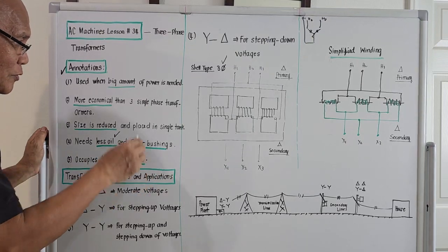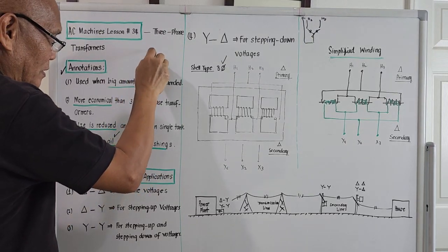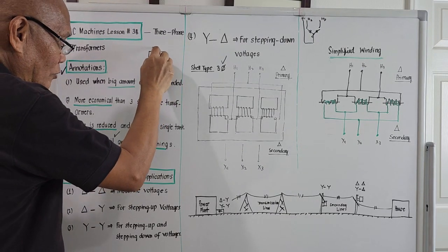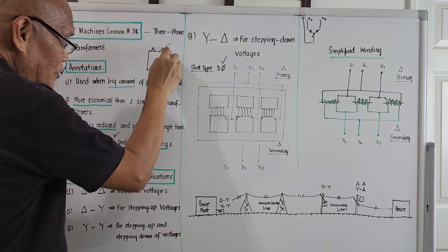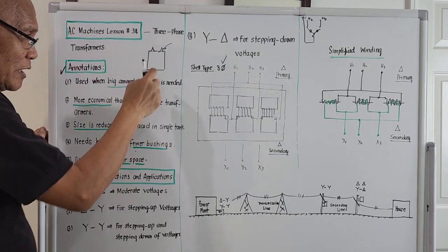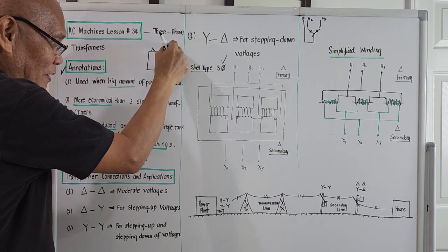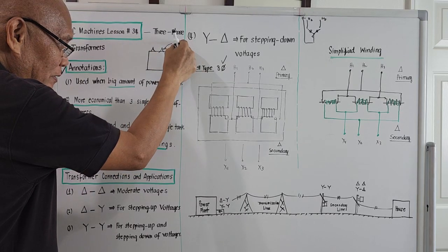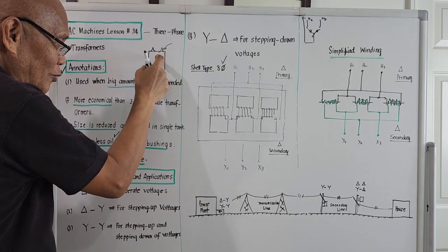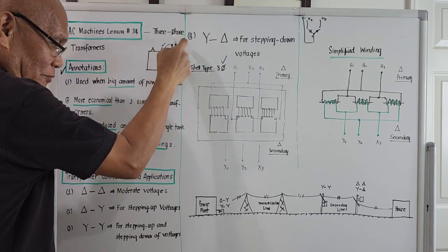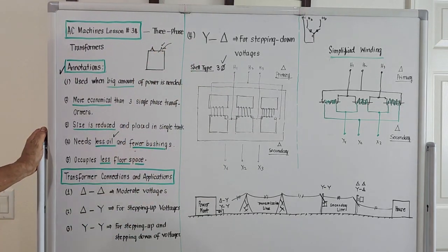What are bushings? Considering single-phase, there will be two bushings, right? Bushings are actually just the insulator between the terminal of the transformer with respect to the winding inside. So this is just an insulator. I think it's just a porcelain thing, right?